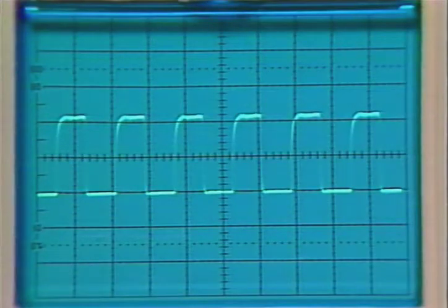We'll talk in detail about the display system first. The first thing one sees when looking at the CRT is the graticule. It's the grid of lines on the CRT faceplate. The graticule is the reference for your measurements. High-quality oscilloscopes have this graticule on the inside of the faceplate.